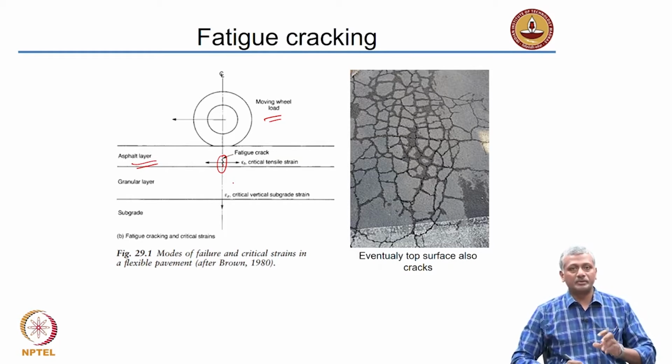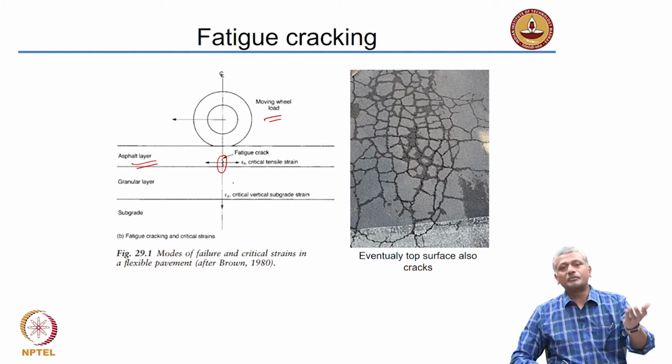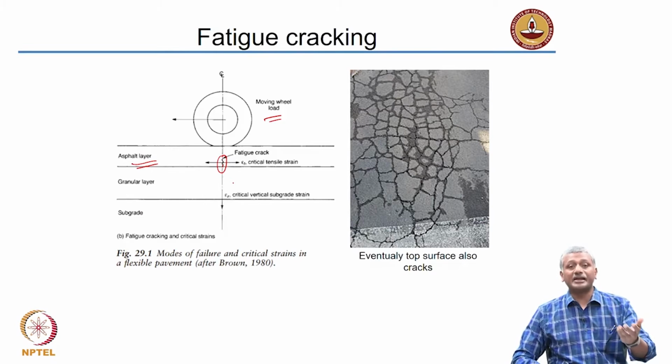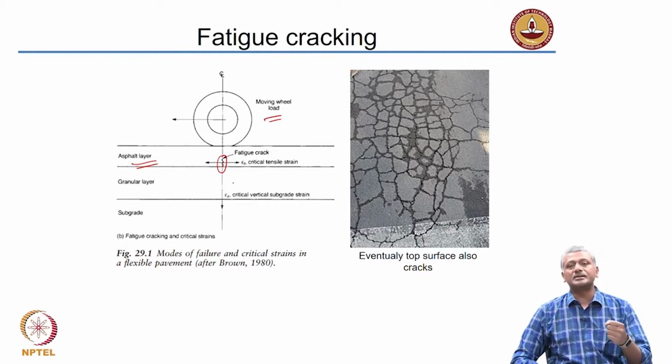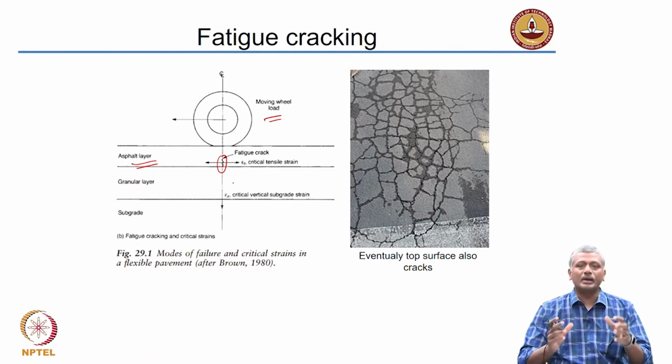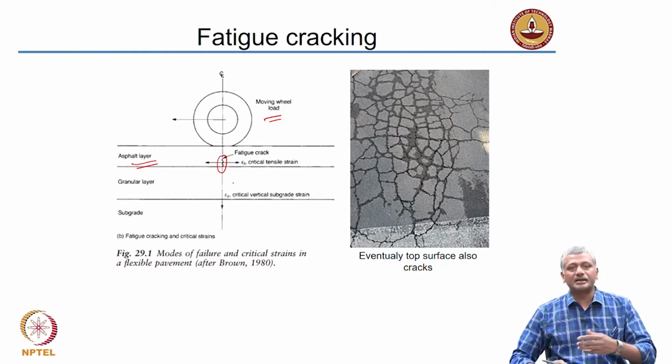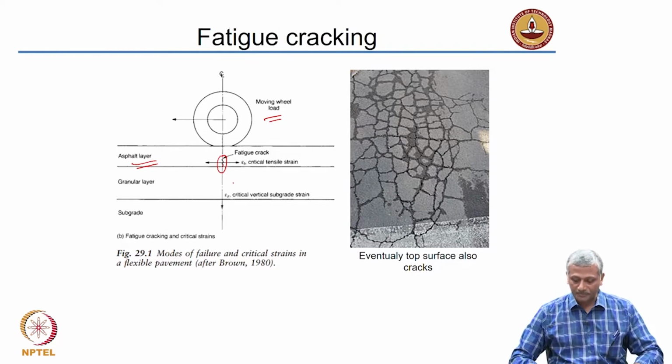So, you need to ensure that you are testing this aspect of the asphalt concrete before utilizing it in a specific pavement. Also, the needs of the asphalt concrete will obviously depend on the type of pavement that you are making. Is that a national highway? Because there we expect all kinds of vehicles. The heaviest vehicles will be there, and you need to consider the tonnage brought in by the heaviest vehicles and convert that to the equivalent number of units of vehicles that will pass over that given cross section in a certain period of time. And based on that, you need to select your material properties in such a way that it is able to match the requirements of that particular road, right.